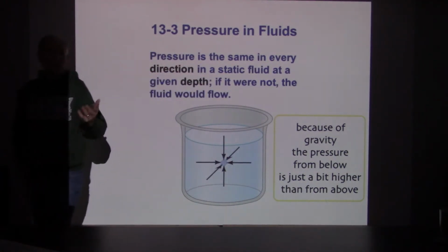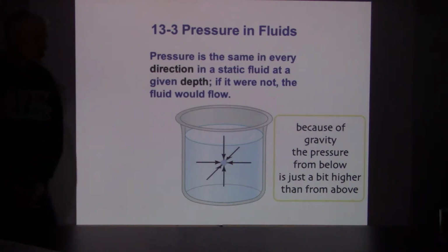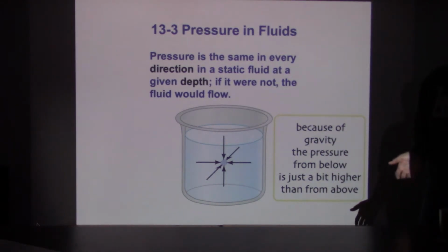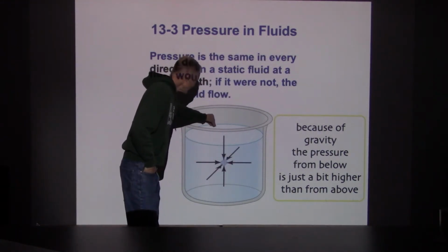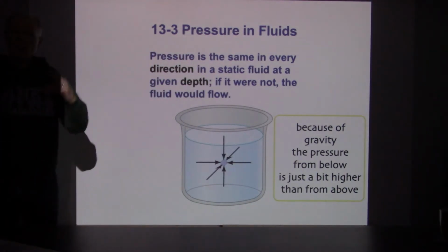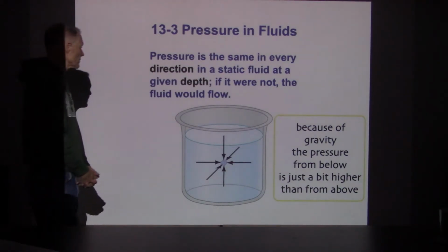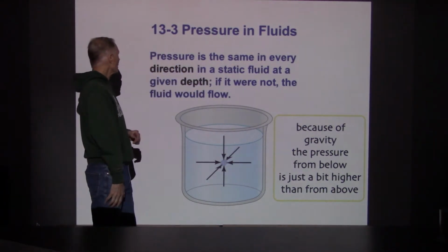It's not just the fluid in the middle that's under pressure, it's the fluid everywhere. So all the molecules are bumping into each other, everybody's exerting pressure. So the pressure is not just at the sides, the pressure is throughout the material. Now we could measure the pressure by dropping an instrument into the fluid, and maybe the instrument has some springs inside and it's compressible and it reports how much pressure is acting on it, how much force it's experiencing. But think of it that way. Wherever you are in the fluid, there's going to be a certain pressure there.